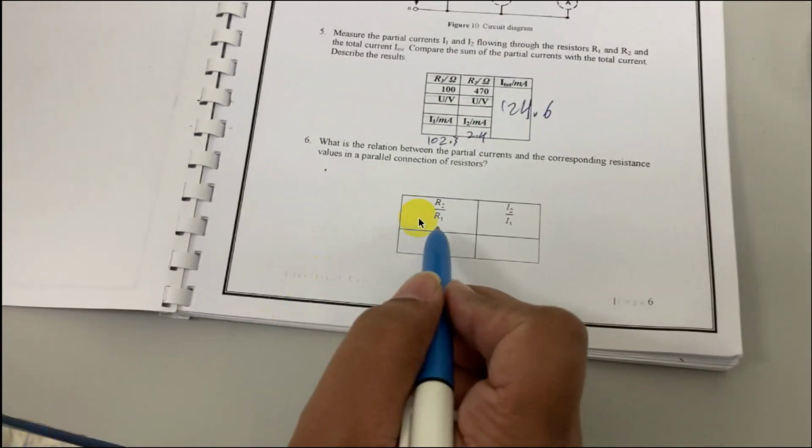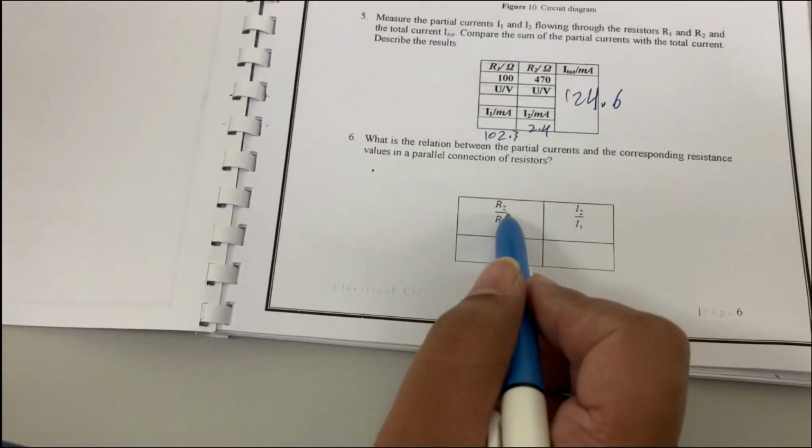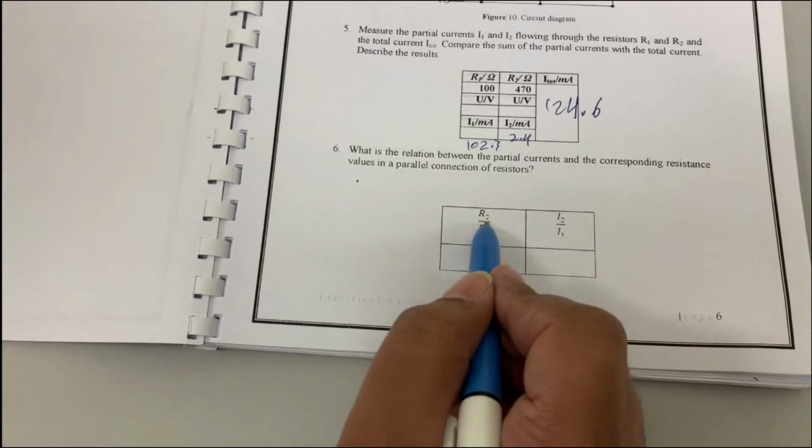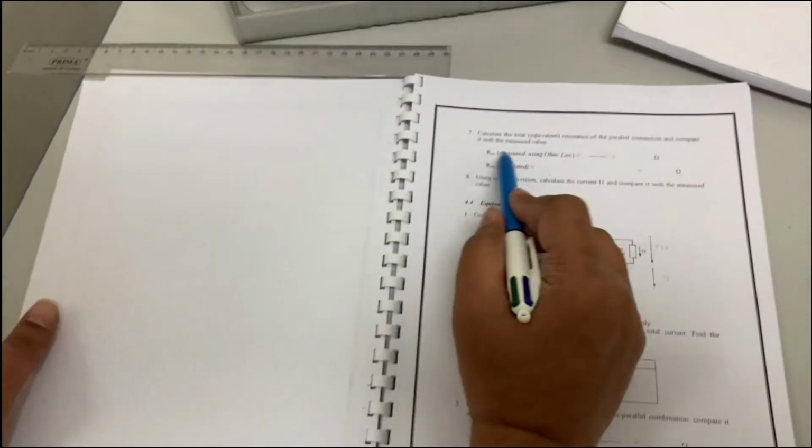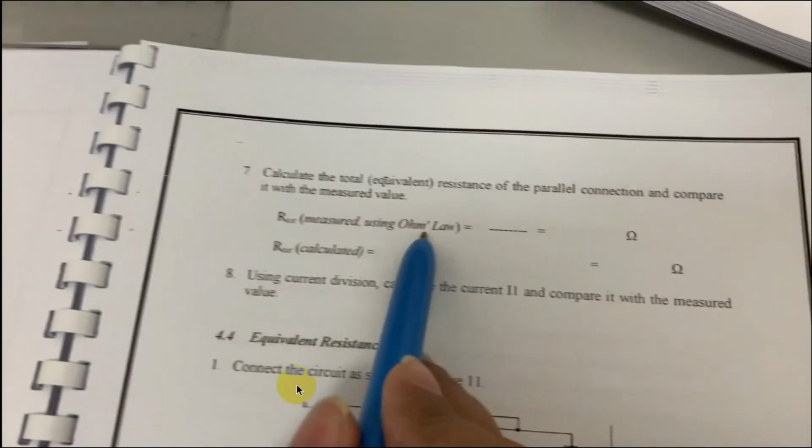Again the same calculation: R2 by R1 is 470 by 100, which is 4.7. I2 by I1 is, I2 is around 21.4 and I1 is 90 point something. Just take the values from the tabular form and do the calculations. So hence we conclude our experiment. Okay, the 4.4 equivalent resistance, we just